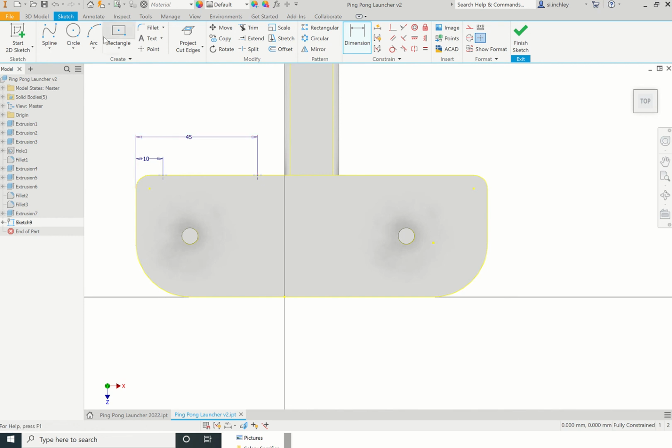Yeah, that'd be fine. 45. Okay, select my arc tool. I'm just going to click on there, and then now I can click on there, and now I can just bring that up. Okay, and maybe put the dimension that you actually want. This is the radius it's calculating as it moves along, and it's quite nice to get an exact dimension. So I'm going to change that to 25 and see how that fares.